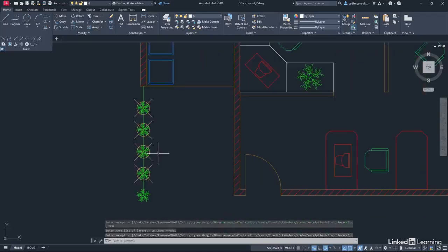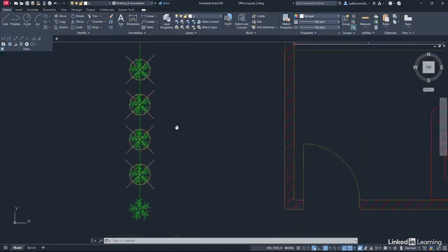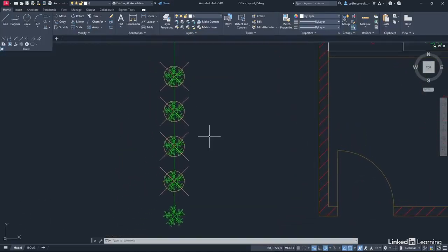Now, what I'm going to do here, you'll notice as well, when I zoom in and out, can you see that 5% in relation to the screen size? Where I've zoomed in and out, they look really big. Just type regen and press enter. That will regenerate the drawing. Can you see they're now 5% of screen size again? It's quite clever. Saves you having to worry about the size of those little points that you've created on that nodes layer.